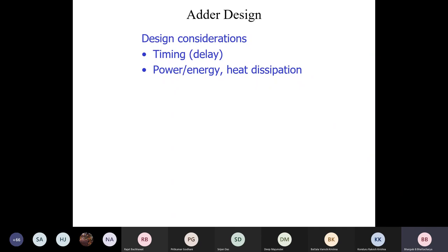This is very important because this is a logic circuit. These are outputs and inputs of different gates, and in a circuit there are hundreds of thousands of such lines or logic nodes. They change from 0 to 1 and 1 to 0 continuously when the system is functioning, and whenever there is a transition, they dissipate energy. So the chip becomes excessively hot. You need an appropriate mechanism for heat dissipation, and an appropriate logic design technique so that those transitions are reduced.